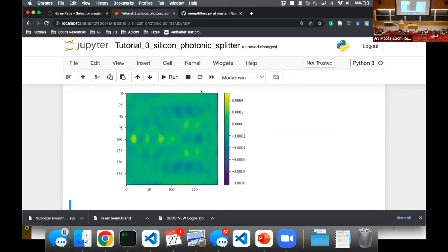He says, are there situations where you use a different filter from conic? I know Meep also has a cylindrical and a few other filters. Yeah, good question, Ben. So as we saw, Meep does indeed have lots of different filters. And there's different reasons you would use different filters based on what you're trying to accomplish with respect to, for example, minimum feature sizes. Okay, if you wanted to incorporate a minimum feature size constraint, that constraint is based on the underlying filter kernel. And maybe the mathematical constraint that corresponds to that filter might be better conditioned for a particular problem, for example.